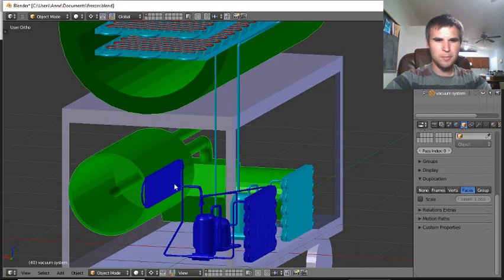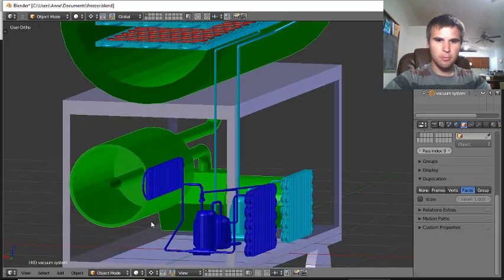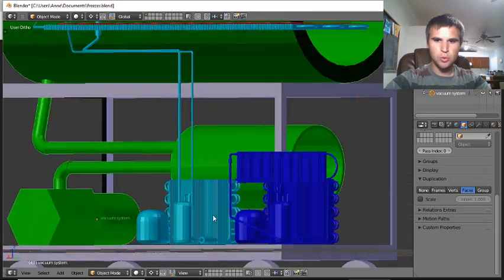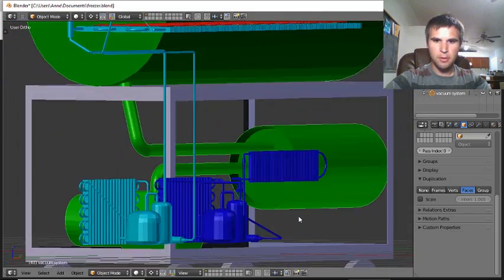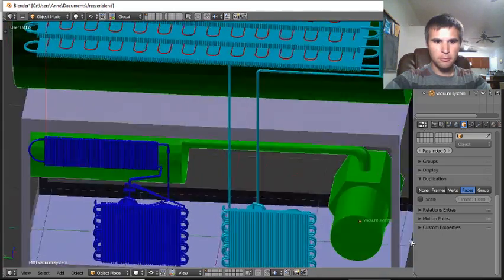We'd probably want to reposition this, and in reality put the evaporator coil in front of this tube so that the material was forced to travel through the evaporator before it could even get down the pipe, increasing the chance that moisture will be captured.